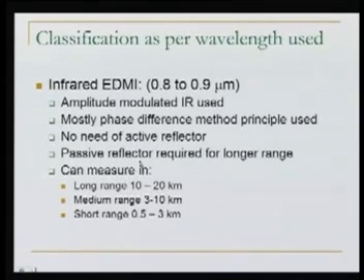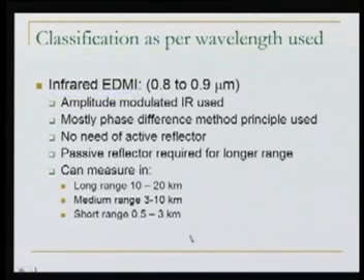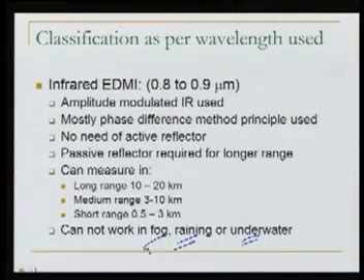These infrared EDMIs come in various ranges. They can measure in 10 to 20 kilometer range, 3 to 10 kilometer, or maybe half a kilometer to 3 kilometer. So all these ranges they can take the measurements in. There is one problem about these infrared EDMIs, that is because infrared gets absorbed in water. So in case of raining, underwater, or maybe in foggy conditions, these infrared EDMIs cannot be used.